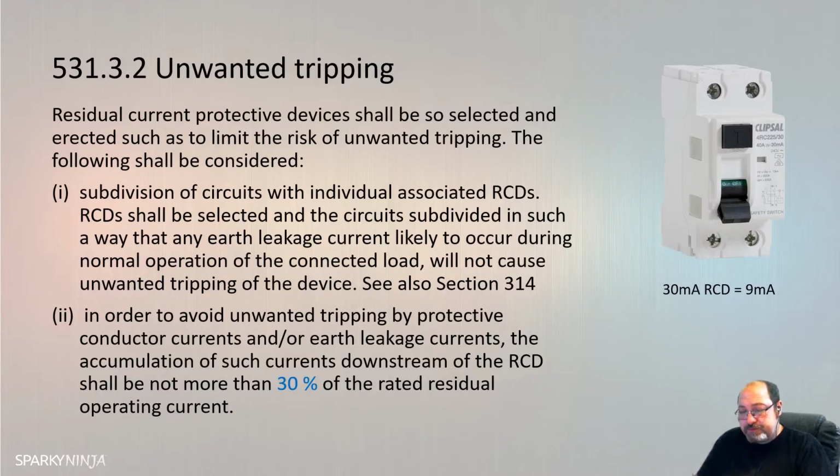So there'll be some circumstances, laboratories and some other equipment where they've specified plant and they say, here's my plant, get me a circuit to that plant, then you can do this. That's absolutely fine. But what it's asking us to do is determine the value of protective conductor current at this point in the system to decide if we actually need more than one RCD. Which isn't a very practical way to approach it.